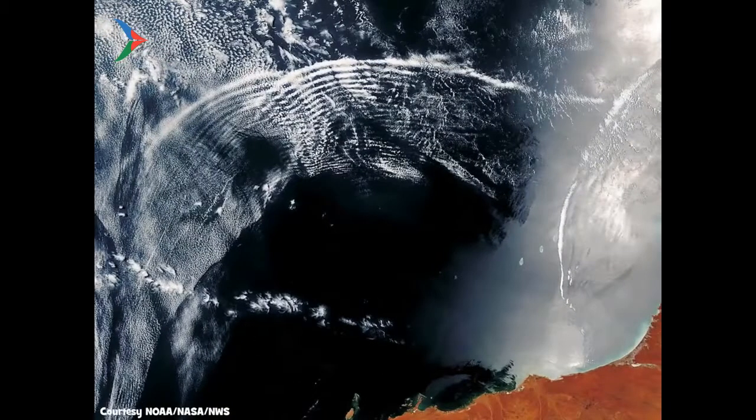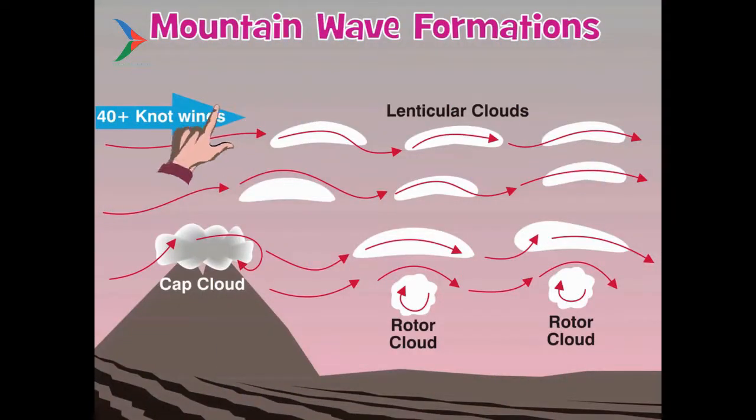The standing wave is very similar to the wave which appears when a long rope is given a good shake at one end. The wave pattern appears to travel the length of the rope, eventually dissipating in a flip at the end. Mountain waves do something very similar. As wind, usually with a velocity of 40 knots or more, encounters a sufficiently large mountain, a perturbation or shake of the rope occurs. A wave pattern is induced in the once smooth-flowing or laminar air. This pattern sets up a series of waves in the downwind direction, with valleys and peaks that remain stationary.